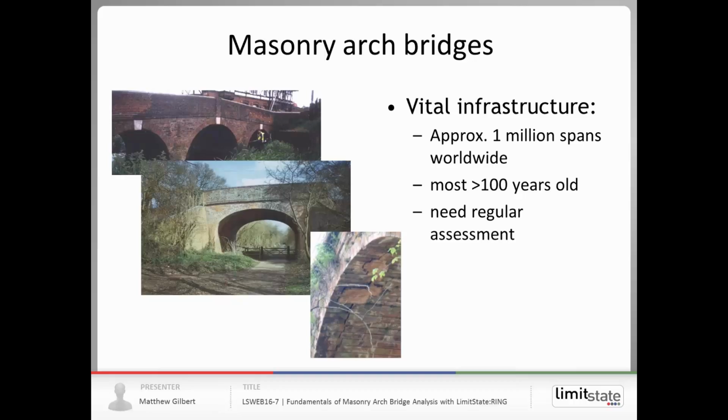Rural roads, railways, we have a huge proportion of our bridge infrastructure formed using masonry arch bridges. Typically we're talking about structures which are well over 100 years old, and they need to be assessed to ensure that they're safe and capable of carrying current and envisaged loads.